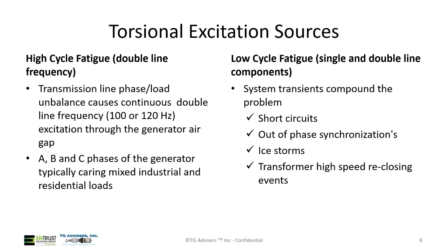So that's that gap between the stator and the generator rotor, and it will excite certain modes if they are near 120 hertz on the rotor train. So what can occur when that happens is high cycle fatigue, so you have a lot of cycles pretty quickly, and we've seen in industry over the many years that this is known, especially early on.